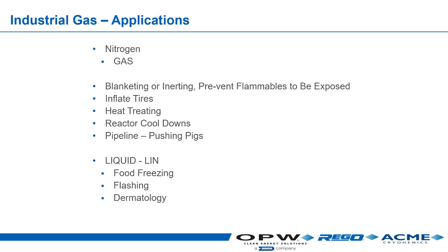The industrial gas companies came in with a nitrogen service pumper truck with liquid nitrogen. They would introduce and control the temperature with warm nitrogen. So they turn off the furnace or heat treater, hydrocracker at the refinery, then introduce nitrogen and control the temperature, slowly reducing it. Within 24 hours, they could get a human being in there to fix what needed to be fixed.